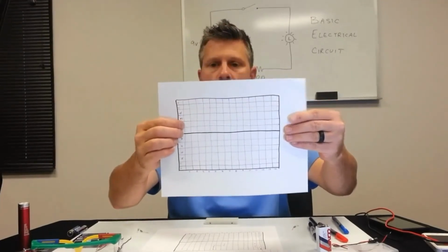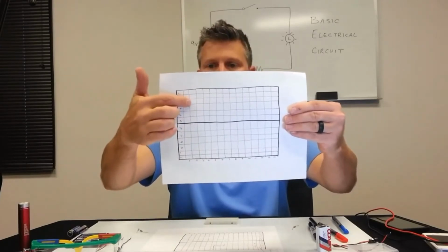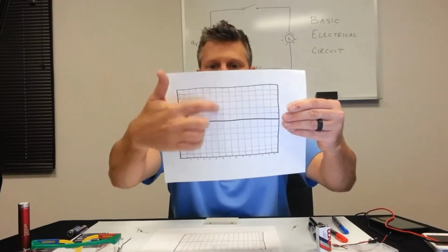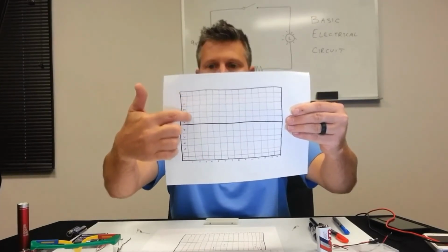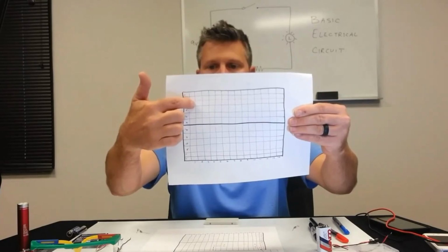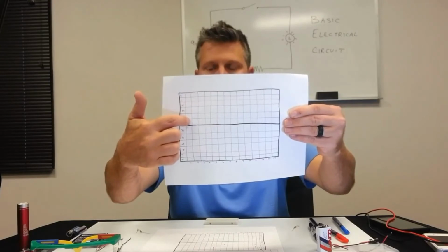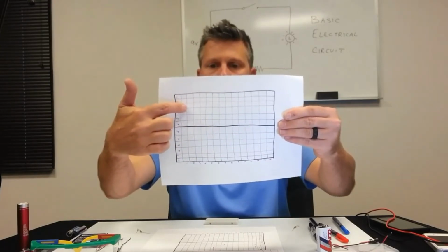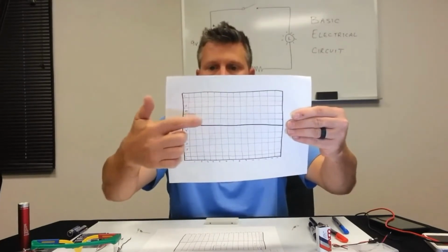Everything below here, instead of running horizontal, it runs vertical. So all of these will be connected. So anything that I connect in these boxes is automatically going to connect. So if I run this positive power to this side, all 4 of these are going to have some positive current flowing through them. They do not, however, touch horizontally. So these go horizontal, these go vertical.